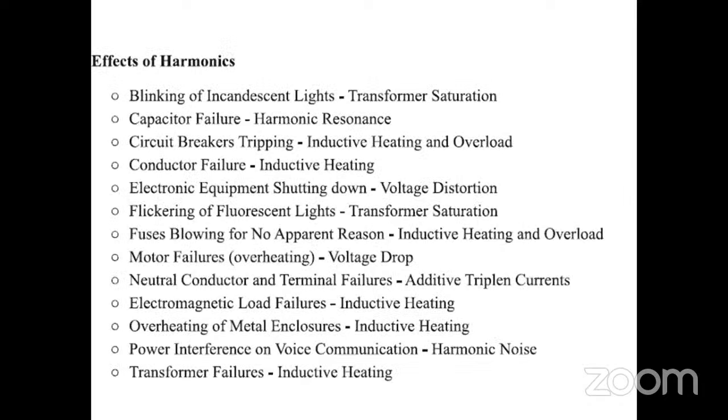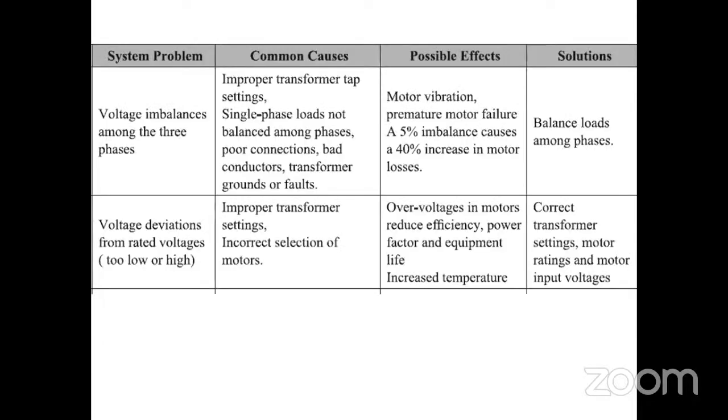Effects of harmonics, you can read it, sir. All these things, and the causes are listed. We will see one final data system problem: voltage imbalances among the three phases. What may be the causes? Improper transformer tap settings, single phase loads not balanced among phases, poor connections, bad conductors.